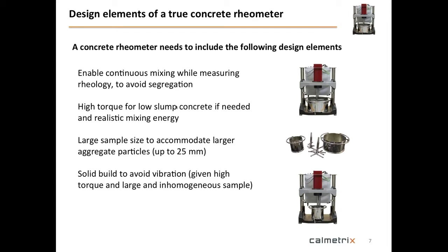We would like a high torque, because the existing concrete rheometers that you have in the market, the ones I mentioned, Viscomat, Rheocad, ICAR, et cetera, all of them need a slump of at least 100 millimeters or 4 inches. Below that, they cannot handle the concrete. The concrete is too viscous. Well, with a higher torque, you could very likely handle concrete all the way down to 0 slump. Why not? Or dry materials, or roller compacted concrete.